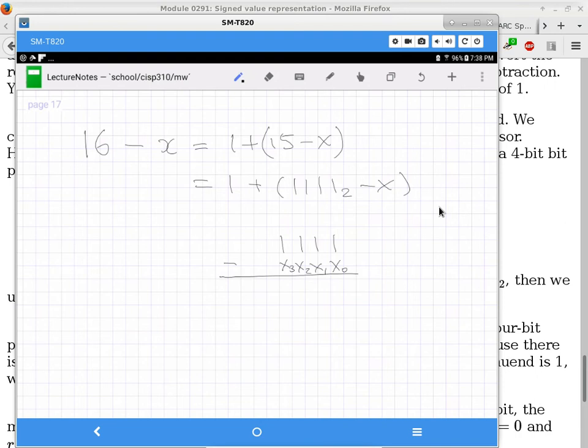Because we've already reached the maximum that our 4-bit system can hold. We're subtracting from that. You can also look at it from the perspective of the borrow function. Remember, the borrow function is the negation of the first and the non-negated version of the second. We are looking at the negation of ones. It doesn't matter which column you're looking at, we're negating 1. What is the negation of 1? 0. 0 and whatever is 0, which means there's no chance we can actually have a borrow.